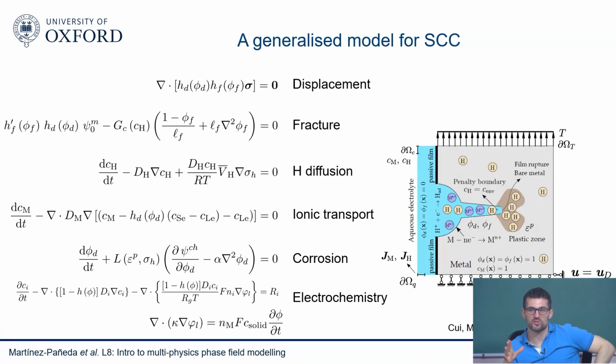So it's a very complex problem where you don't know. Sometimes under certain regimes hydrogen dominates and the crack is growing mostly due to hydrogen with maybe some help from the corrosion process that you see, for example, in cathodic protection conditions. And there are some other conditions you may have, for example, in the anodic regime, where you have a little bit of an uptake of hydrogen plus the dissolution of material. So in some areas they are more synergistically combined, and in other material environments, it's anodic dissolution that drives everything altogether. So this has always been a nightmare, a bit of a headache for the people working in this community, because they don't really know when cracks are growing due to hydrogen, when they grow due to anodic dissolution, when they grow due to the combination of both.